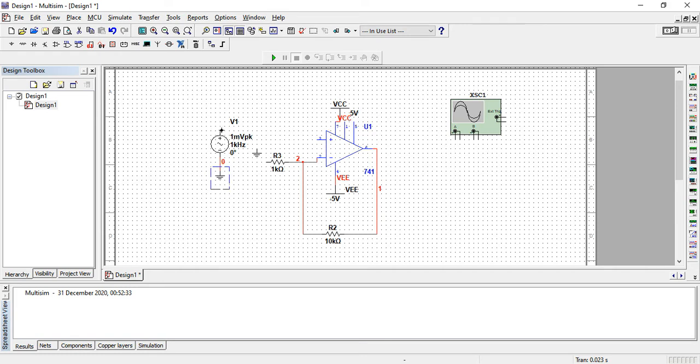I'm using the same signal, and I'm connecting it with my terminal number 2 and grounding my inverting terminal. So the feedback is on your negative terminal which is grounded because we are using it as an amplifier, not an oscillator, right? So again, here this terminal and my ground, and here your input signal will go, which is on your terminal number 3 and your ground, right?